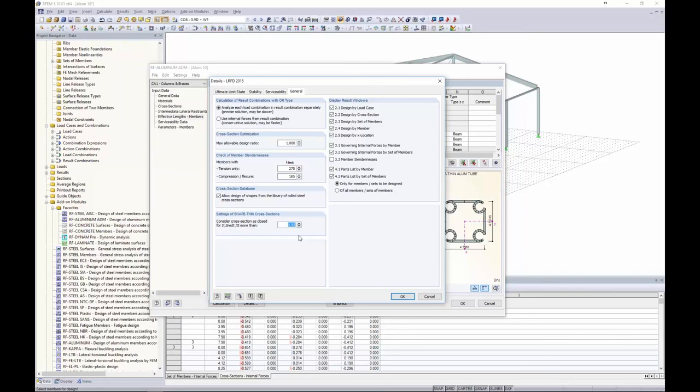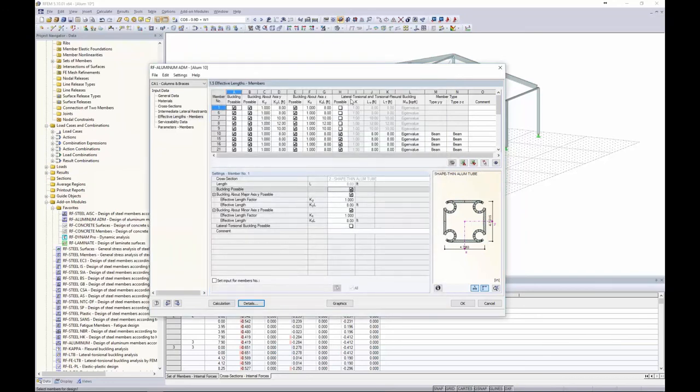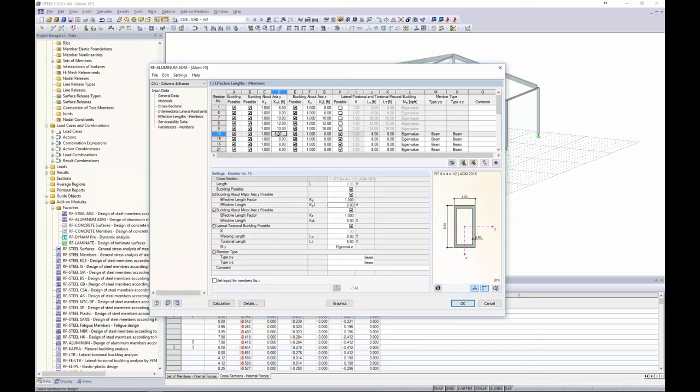You can adjust this ratio, and then you will be allowed to do lateral torsional, flexural torsional buckling. But for now, that is the reason why these are unchecked. For a square tube-like member, torsion is probably not so much of a concern. For the other hollow sections here, the 8x4 members, we also could uncheck torsion if we wanted to, or we can leave this checked just to take a look at it.